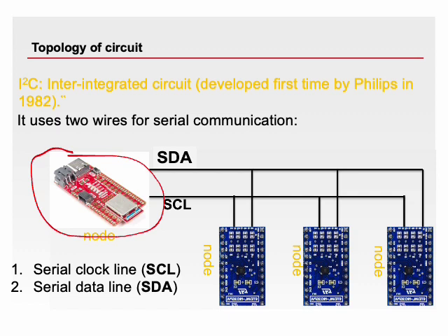The master is connected to all slave nodes through 2 lines of communication, namely SCL, serial clock, and SDA, serial data lines. The master device generates the clock signal on the SCL line and uses the SDA line to transmit data to slave devices or receive data from them.